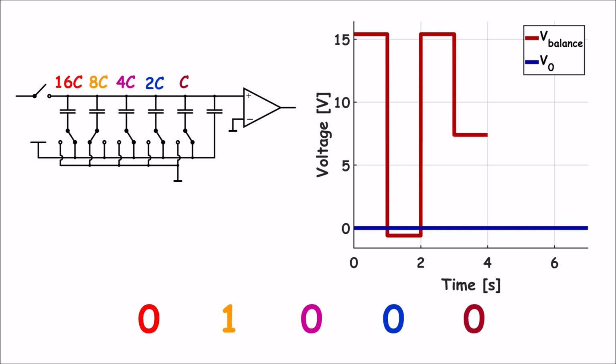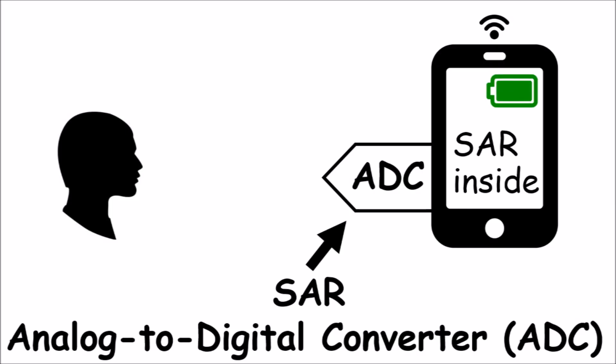Next, the second largest capacitor is toggled. The algorithm is carried out as shown in the scale analogy. The comparator helps us check whether the balance voltage is positive or negative, and thus whether or not previously added capacitors should be switched back out, or if additional capacitors need to be switched in. Now that the circuit has been explained, we will show a practical example.